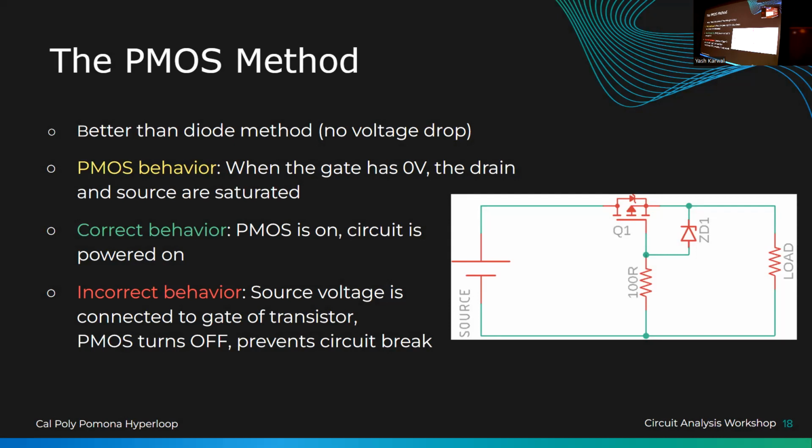That would be the cutoff region. A simple way to think about it, and how I learned PMOS, is this: if you go into 2200, the microelectronics course for those who are not EC majors, you get a whole bunch of random stuff thrown at you and the numbers are just insane. PMOS and NMOS are in the family of logic level transistors, and when you're using them in projects, most of the time they'll be logic level. That means in order to turn them on or off, you'll use 5 volts or 3.3 volts sent through the gate. It's like the gatekeeper of transistors.